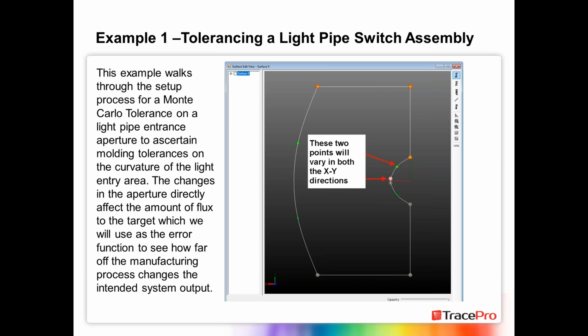Now, if you wanted to, you could set this up as an asymmetric profile. In this case, you would be able to change the bottom and the top, so they would change differently. But pretty much in the plastic injection molding process, due to the thickness of the different materials, this is where you're going to have a discrepancy. It's either going to melt a little bit more or not melt as much. You've got humidity conditions, you've got temperature conditions inside the building where this happens. That's what's going to change these parameters.